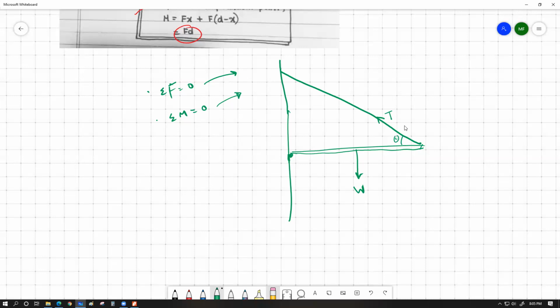So the third force that we always have available in a situation like this comes from the hinge point. This hinge also applies a reaction force on the left corner of the plank in such a way that the resultant of all of those forces, the tension of the string, the weight of the plank, and the reaction force coming off the hinge, together becomes zero. It gives us a zero resultant.